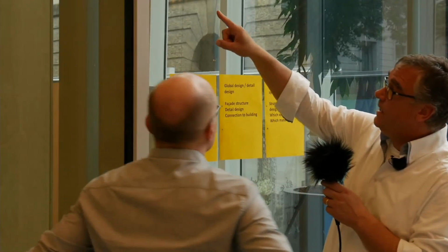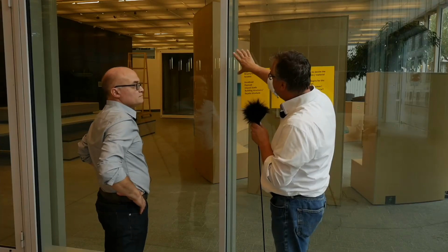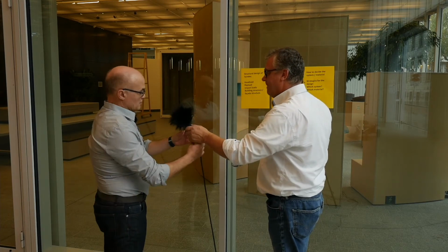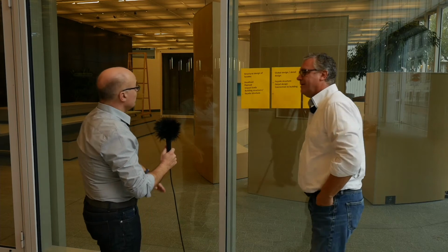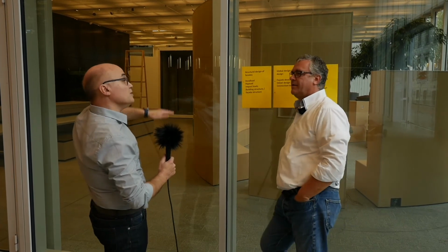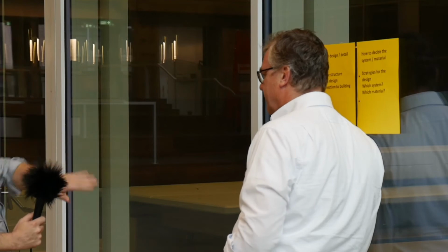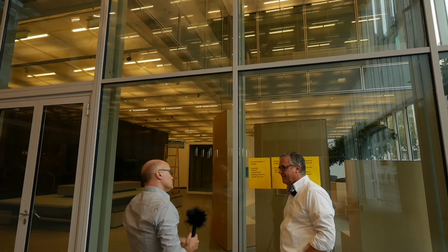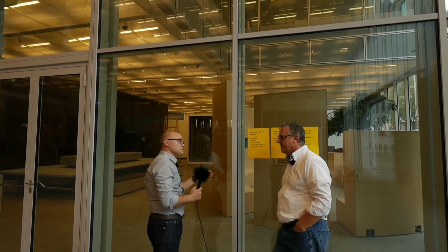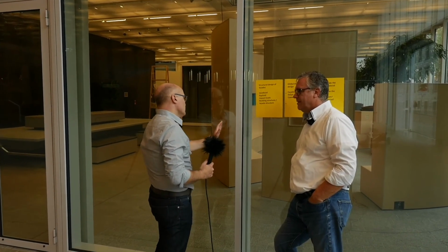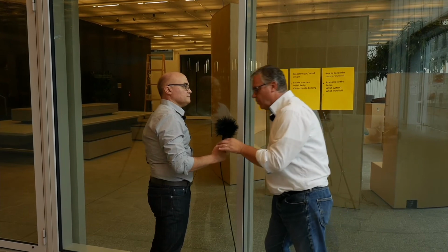And why do we see here an aluminium system and then a steel structure behind? Very good question. This is a particular facade where we have two or nearly three stories high. So the aluminium structure itself, this aluminium mullion, is not sufficient to resist three stories' worth of horizontal load. So it needs an additional, in this case, steel structure to support it. But if this was just one story, you would only see the aluminium. There would be no steel.